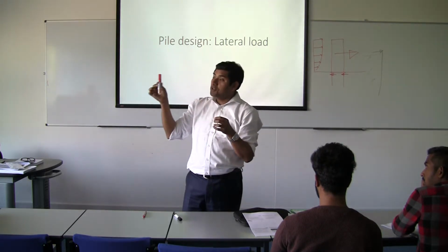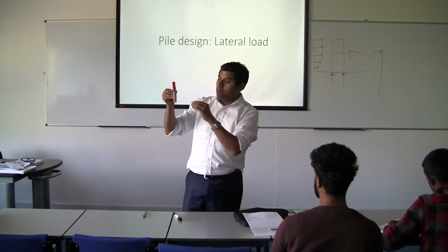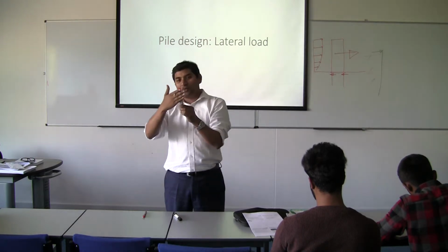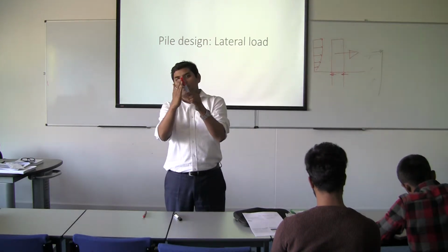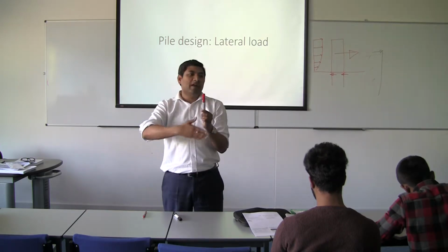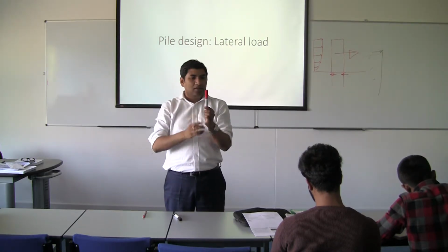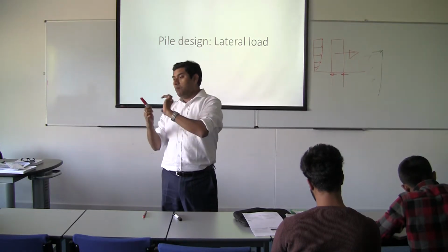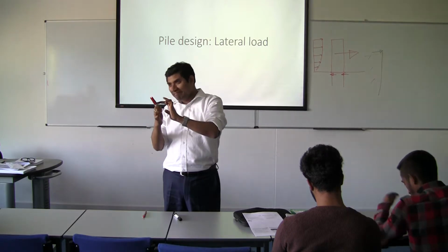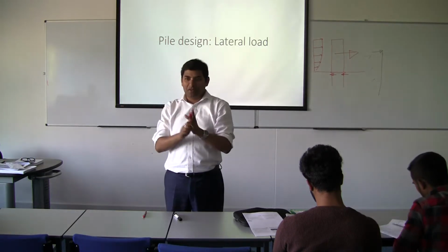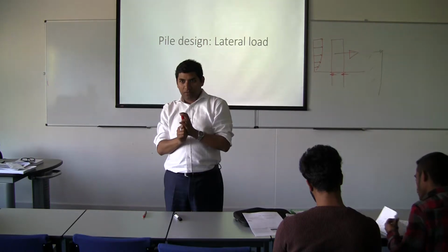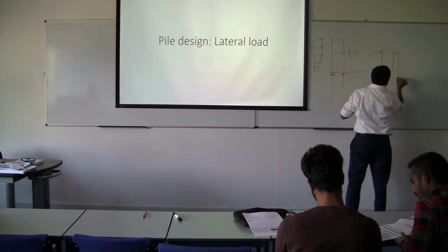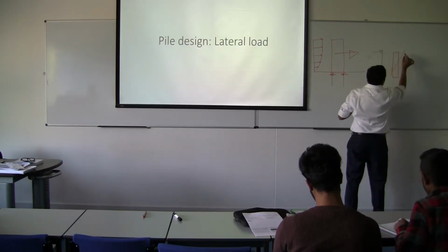For a rigid pile, if it fails, the pile will not fail by plastic hinging or yielding. The soil would fail. You pushed it so much that the soil around it has yielded, so it went to its yield strength, right? In this case, the pile will not fail. The pile would fail as a whole, but the pile as a member, like a beam, will not have a hinge formation. So what I mean to say is that you will see the pile failing like that, right?